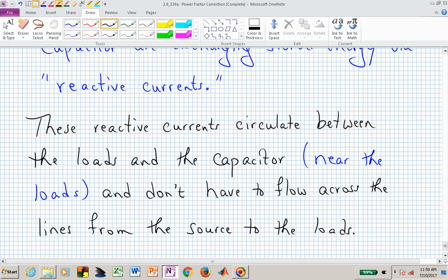So now a company might be in better shape if they actually build in some capacitive banks when their circuitry or their loads are heavily inductive. They may get charged less from the power company since the power company is having to produce a smaller power to deliver to that particular load.